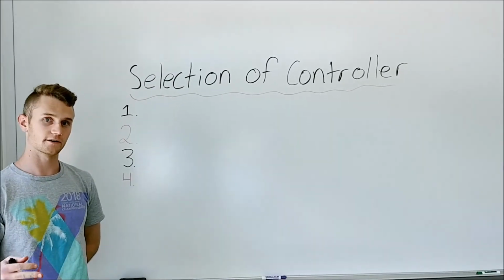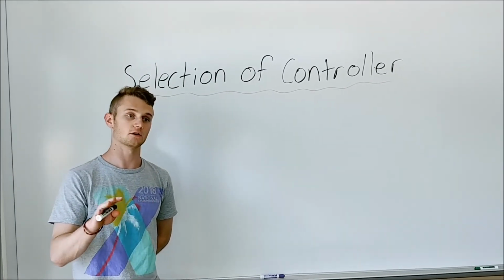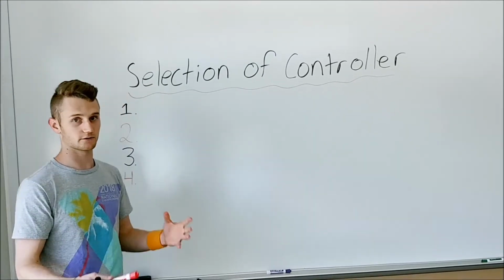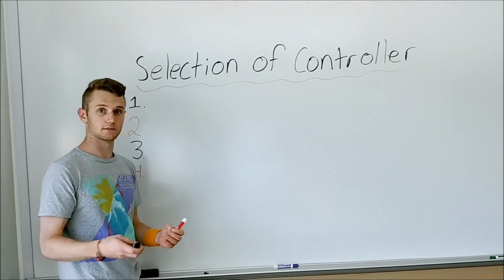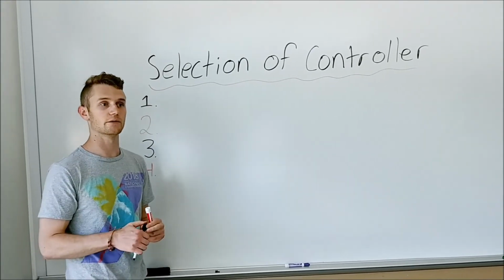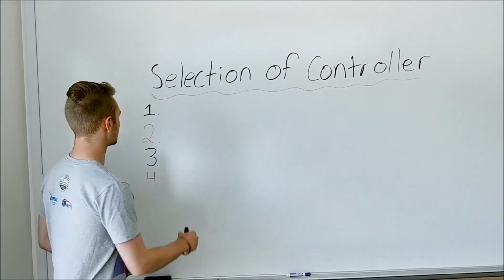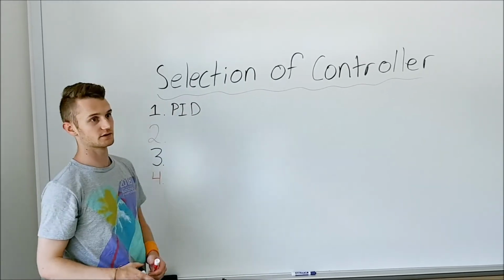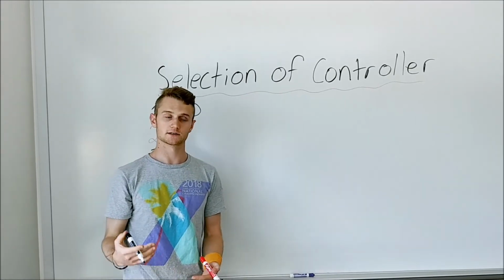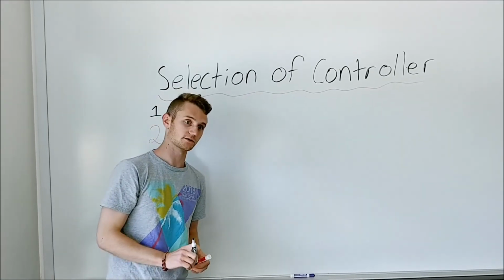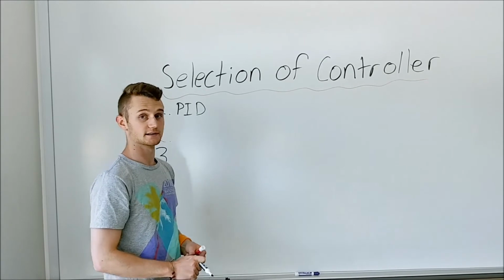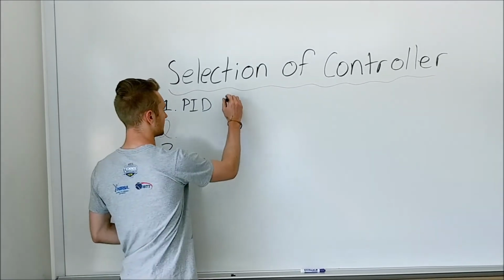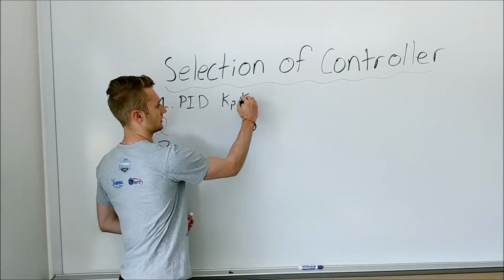So our initial evaluation of the controller selection stipulated that we'd use a PD controller to meet our original goals. But after some analysis, we found that we would have to redesign the controller to be a PID controller in order to make the system second order, such that we could meet our goals for the rise time and settle time.